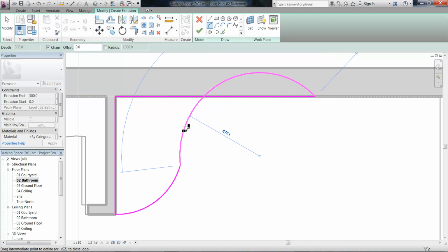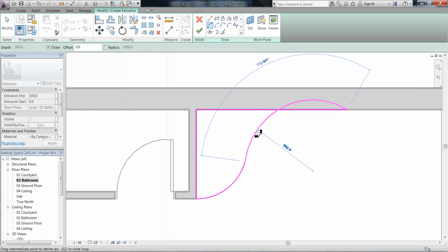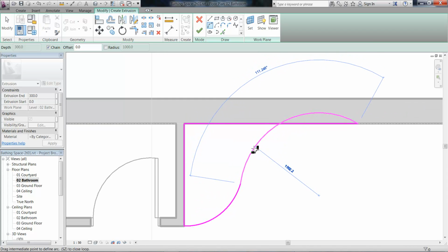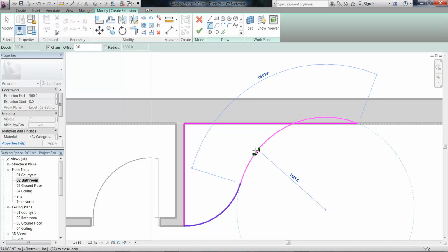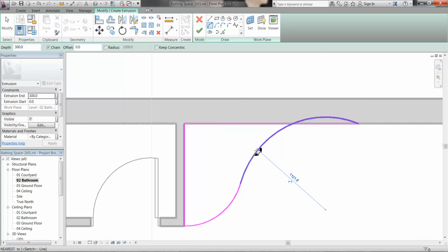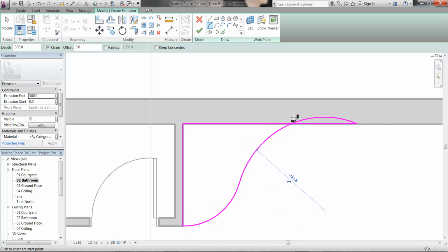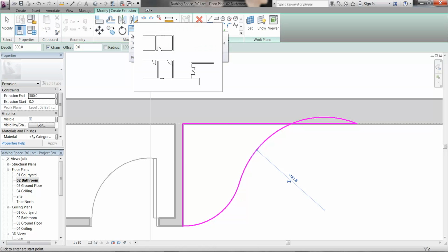So I've got it snapping to the previous curve. You'll see as you move, it'll eventually highlight, there we are, when you get what's called the tangent. That basically means you get a smooth curve. So there, though, I've got now this extra part, like the fish I suppose, and you don't want that. So I've got to trim that off.